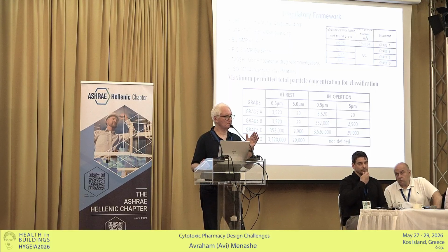Okay, so it's once-through, we bring the air from outside. We spoke about ASHRAE 214, we are speaking about decarbonization. In this case, we are working on 100% makeup air, and we know makeup air is the biggest consumer of energy from air conditioning aspects. So this system is very important in terms of filtration, in terms of maintaining the temperature and humidity, and Stavros described before some ideas about our human body behavior in different conditions. So it's very important to maintain the humidity and the temperature in the halls.